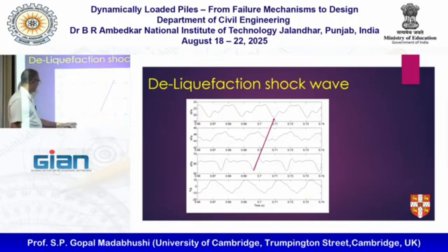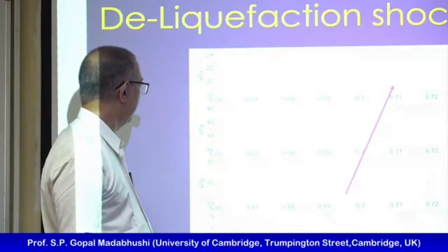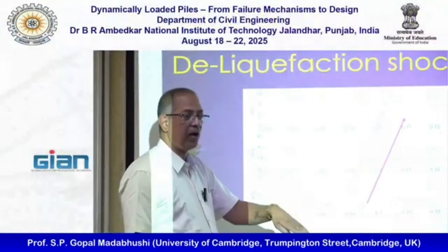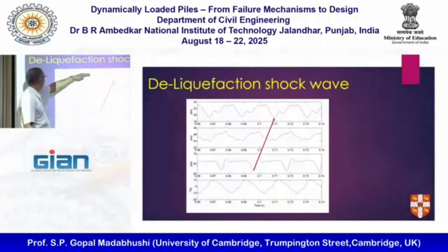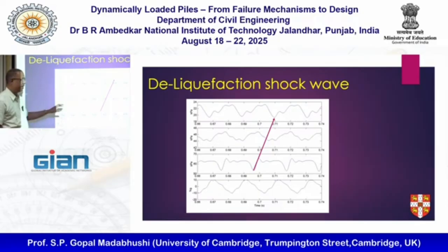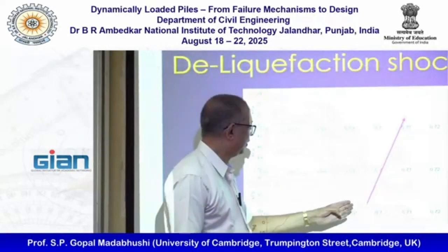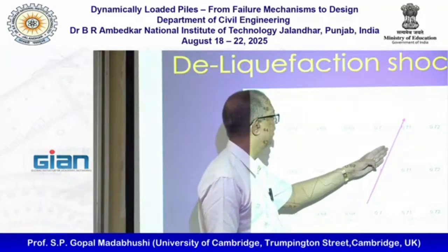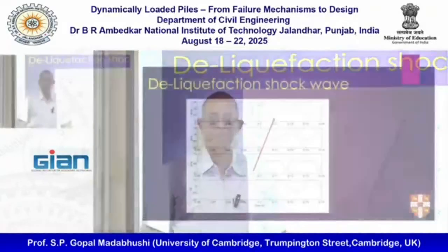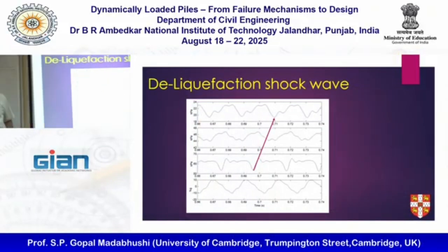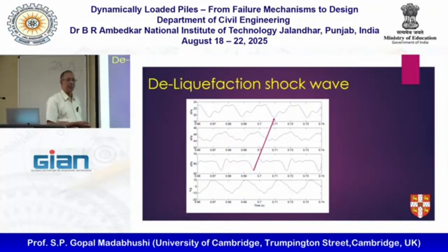This is the earthquake we applied, more or less sinusoidal, and these are the pore pressures along the height, deepest to shallowest, zoomed in quite big. But what you can see is this liquefaction shock wave propagating. So this is not some myth that we created. You can actually see that in almost every centrifuge test we do.